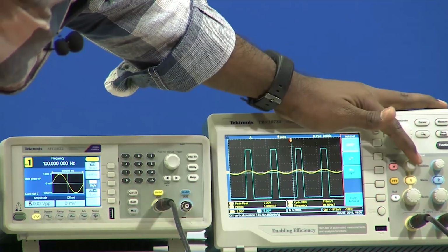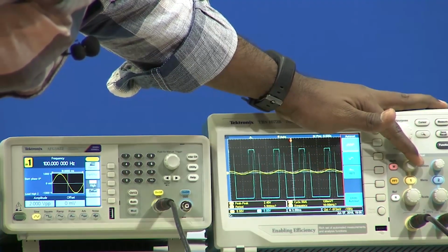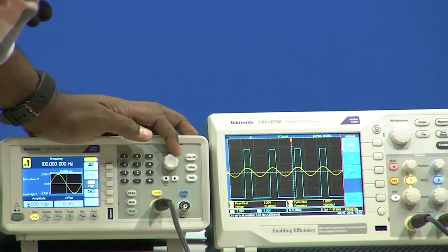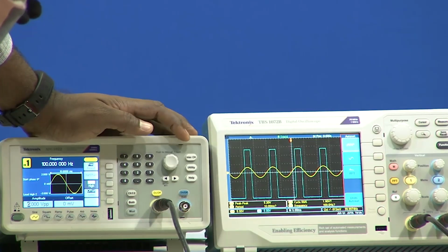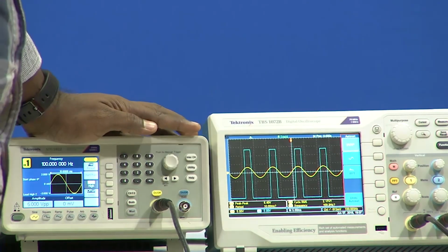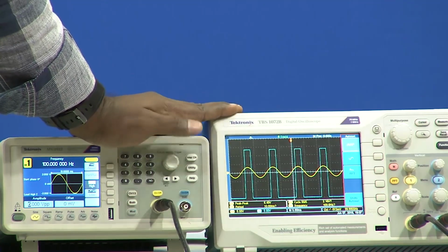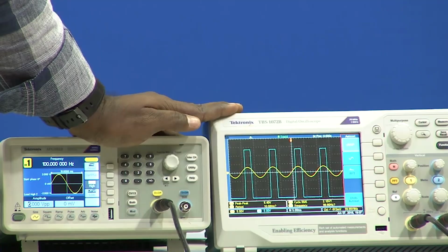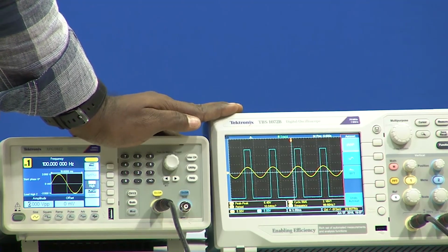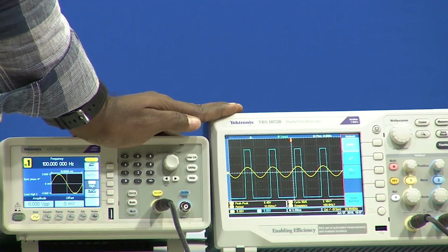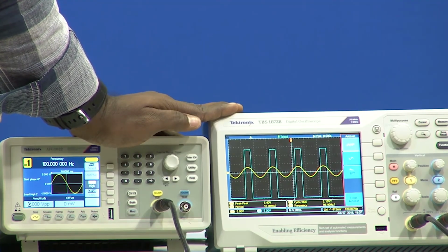Since it is difficult to understand, I will change the input amplitude itself to somewhere around 6 volts peak to peak. So, that means 3 volts. So, here it is clear. Now, if you remember the threshold, the theoretical threshold for 3 volts would be 666 millivolt into 3, but practically we are getting 1.2 volts.